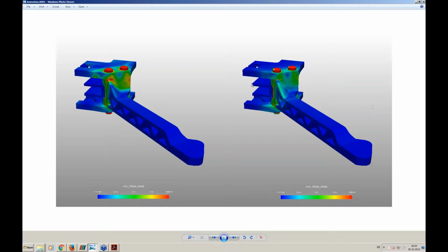On first view, it looks quite similar, but if you take a deeper look, you can really see that, for example, in the area of the screws, or where the arm is, there are some differences. If we now take a look at the result for higher forces, so this is 1.5 Newton, 2.25 Newton, 3 Newton, you can really see that this has an impact. We have a small change in the arm because the lift force is changing. But still there is a difference between the simulations that seems not to be related to the forces. And by the way, left and right side are absolutely the same simulation setup. The reason is really the mesh refinement.